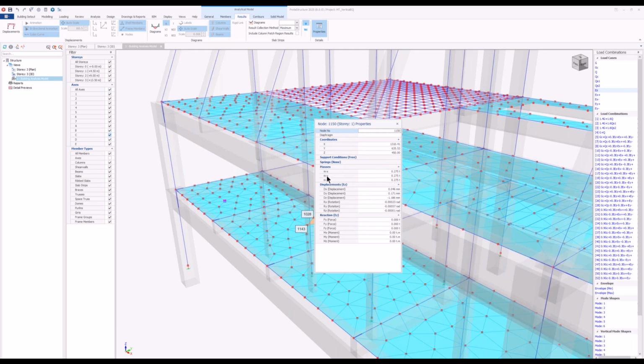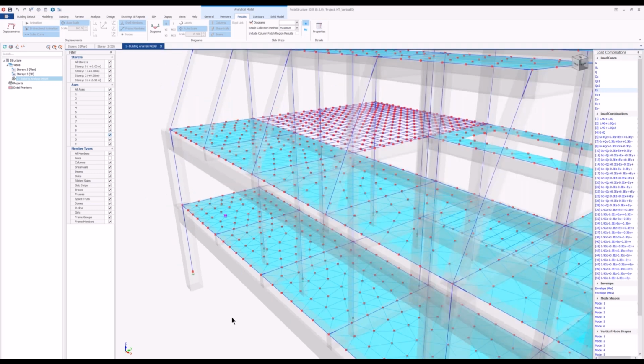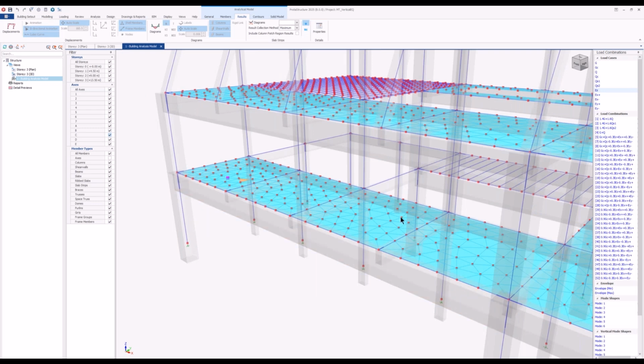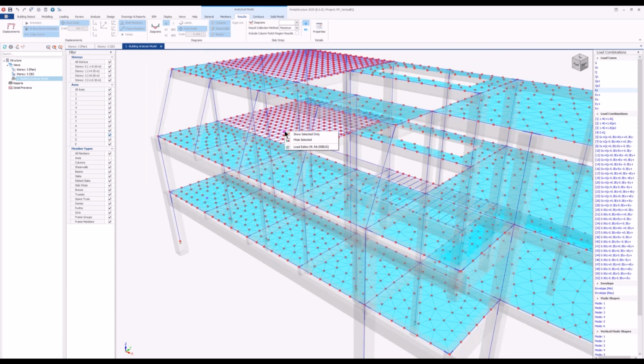So mx and my are required for the lateral analysis, but mz is important because you always have to have some mz mass regardless of the horizontal analysis. And also, if you want to capture the correct behavior, you have to mesh the slab to get the vibration modes properly.